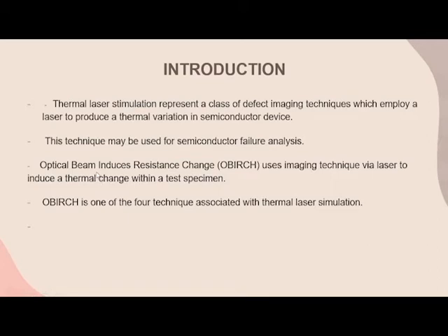Thermal laser stimulation has four techniques. One of them is OBIRCH, and the other three are thermally induced voltage alteration (TIVA), external induced voltage alteration, and Seebeck imaging. But now I will focus on OBIRCH.